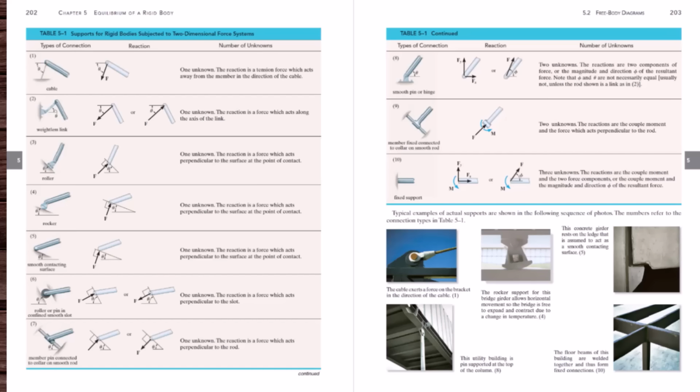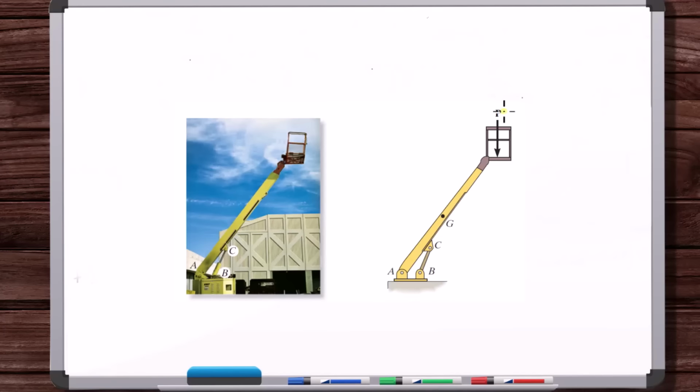So the force from the wind on the skyscraper, that's an external force. You didn't have to remove a connection. When you brought the free body diagram of the skyscraper structure into space, you didn't have to remove a connection, and the wind force was not associated with a removed connection. The car, the force on the tires: you didn't unbolt something or remove material, or make a slice through a connection through the body. That's an external force. A person standing here, that's an external force. Gravity, that's an external force.